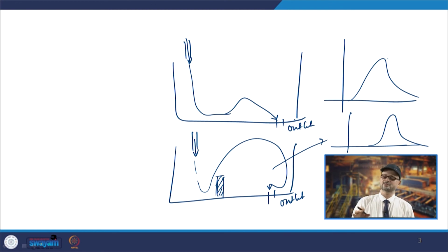Now, with the help of the C curve, we also know in how much time the fluid particle is coming out, and when there is no concentration coming out. Based on that, we try to characterize the space inside the tundish. We divide it into different volumes, like dead regions, mixed regions, or plug regions, plug flow, mixed flow or dead region. This will be found out using these pulse inputs.